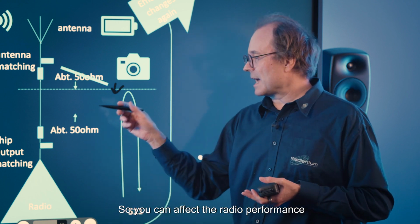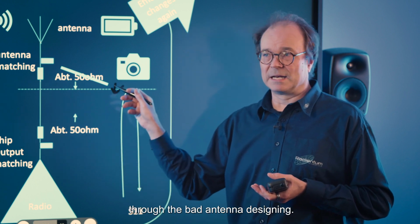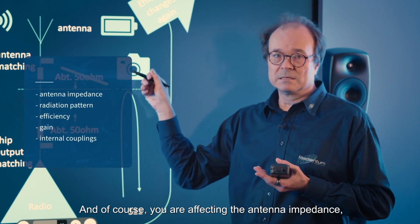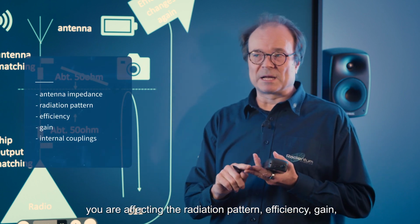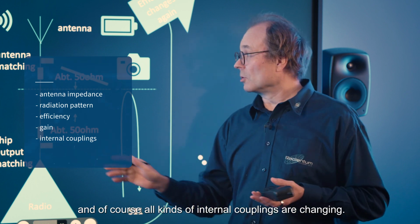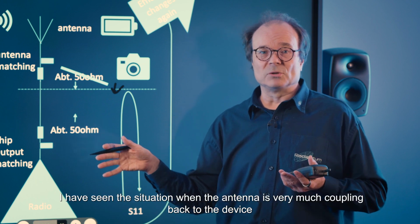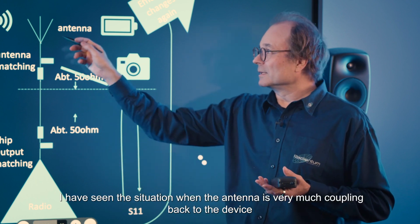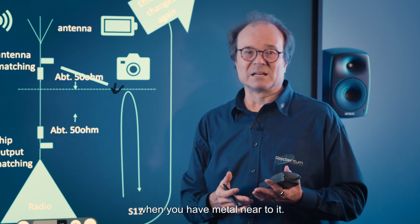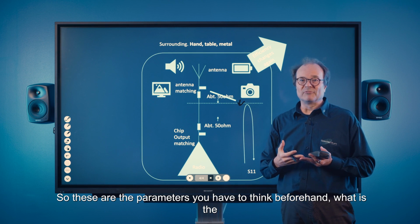So you can affect the radio performance through bad antenna design, and of course you are affecting the antenna impedance, the radiation pattern, efficiency, gain, and all kinds of internal couplings are changing. I have seen a situation where the antenna is very much coupling back to the device when you have metal near it.